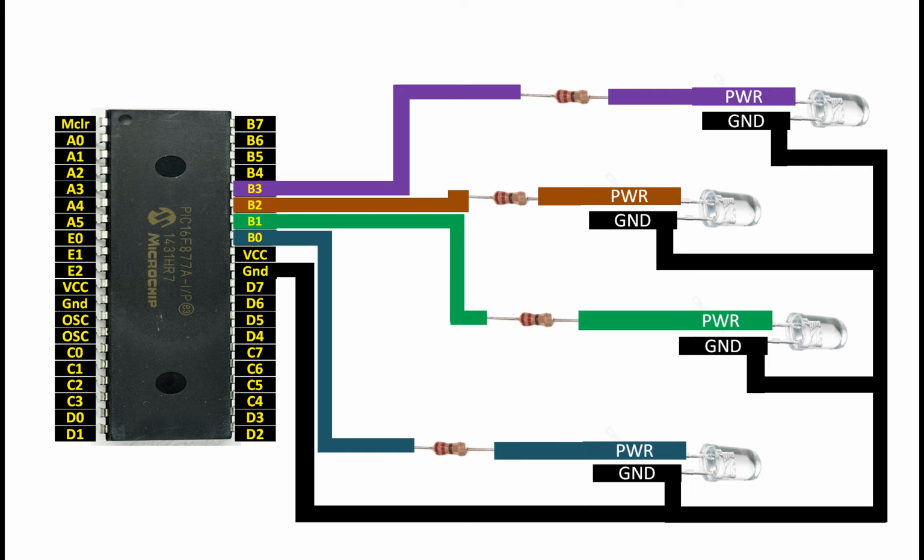So what we're going to do here is simple. For demonstration purposes, I will give port B a certain value which will turn on this LED first. We will blink this LED. Then we will start from B0, this LED. We will use a bit shift operator to the right, and the LED will start moving one by one to the right like this, and we will give a certain delay like 250 milliseconds, one by one, and then it will come back one by one.